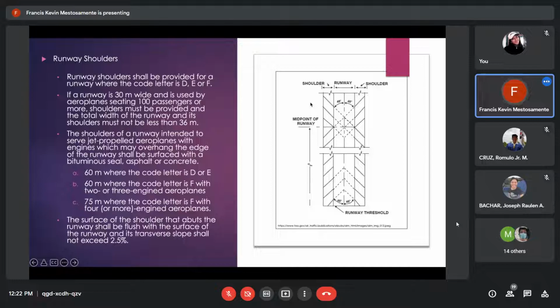Therefore, leading yung runway mo na into slowly destruction ng runway. So, of course, repeated issue, mauuka yung shoulder. If hindi siya cemented, then it will lead to the destruction of the runway. So that's the primary reason kaya nire-required yung runway shoulders to be cemented or asphalt or surfaced is to accommodate yung jet blast ng overhang engines ng mga large commercial aircraft. We have the data, of course, here.